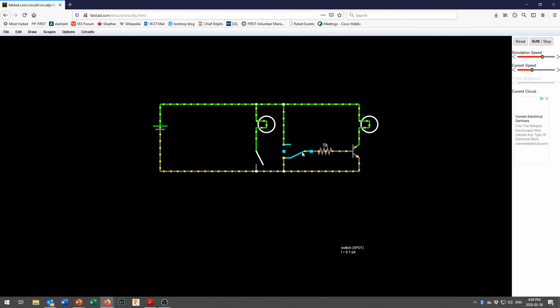So what we can do is switch that over to a high command, and now you can see we've got electricity flowing right through here, and the signal that we would have coming from our Arduino would be right here, would be hugely tiny and not a big deal at all. Totally within the Arduino's ability to handle sending a signal like that, because all your Arduino would be doing is sending the signal to the base, saying, "Hey, transistor, time for you to turn on right now."